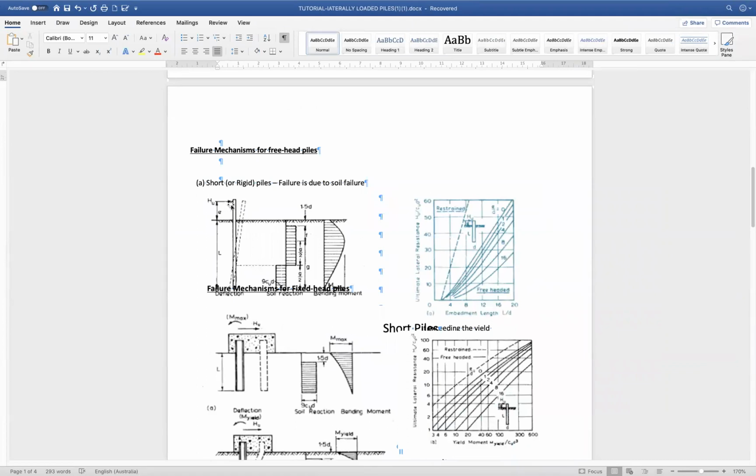So we have here the H ultimate, and we have here the reaction from the soil acting in 2 different directions. We have these forces acting to the left-hand side, and we have the one at the bottom acting to the right-hand side. So as you can see, the one within the length G, which is segmented into 2 parts, G over 2 and G over 2, the top one and the bottom one, these 2 horizontal forces will cancel each other, because that one is acting to the left and that one acting to the right. So these 2 forces here will cancel each other.